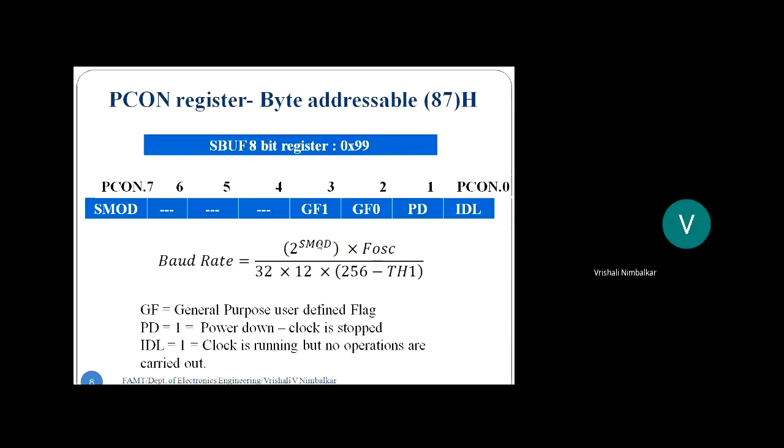SMOD is one of the bits available in the power control register PCON. See here, there is a diagram shown for PCON. The last bit in the PCON register, that is PCON.7, is that bit SMOD.